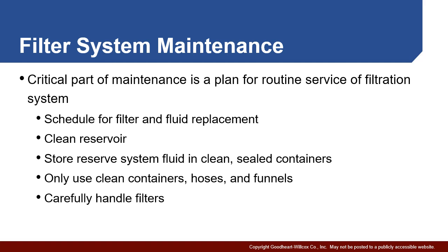But other things that should be built into your schedule and your processes is to make sure that when the fluid is not in the system, when it's being stored, that it's stored in a clean area in sealed containers. And when you're actually doing the filling, that you're using clean containers, hoses, and of course funnels. They are also potential sources of contaminants. So make sure those are all clean as you're putting them together. The thing about filters themselves is that while you're taking them out, you want to handle them very carefully because you want to make sure that all the contaminants trapped in there don't end up separating and falling into the system. So you want to remove them very carefully to avoid any additional contamination.